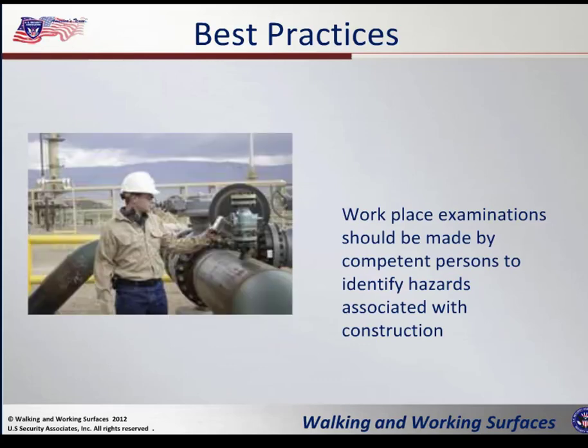Workplace examinations should be made by competent persons to identify the hazards associated with construction. Now, you have to realize that you may have OSHA inspections, any other kind of inspectors that come and visit your site. You need to make sure that your supervisor knows that they are there, if they don't already know. If they don't, then inform them, let them know somebody is there to do a visit, who they are, what kind of branch they're coming from, so that your supervisor is aware of what's going on.